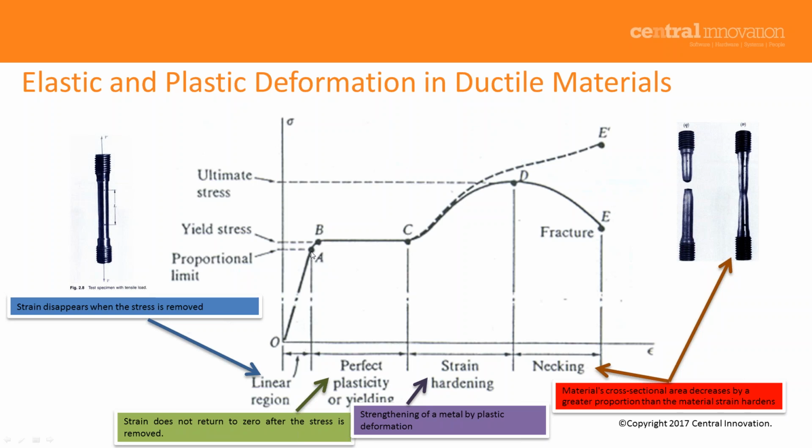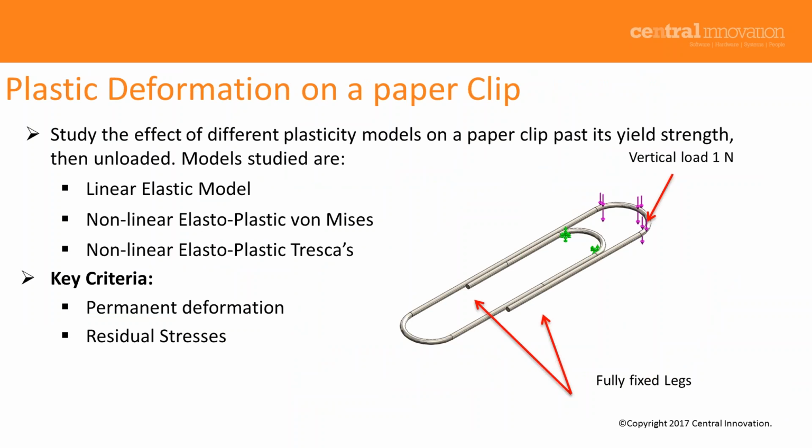In linear static studies, we are limited up to this region. But in nonlinearities, since the relation between force and displacement is going to change and it's not a straight line anymore, it looks like a curve, we need a nonlinear solver and we need a variety of parameters to represent the material response to the loading after the yield point. So nonlinear static study or even nonlinear dynamic studies are the correct study types to capture such an effect.